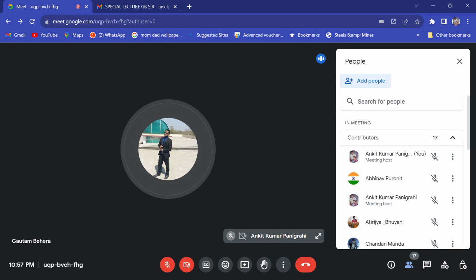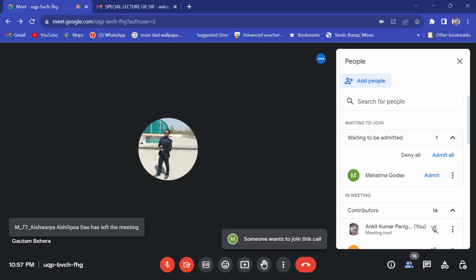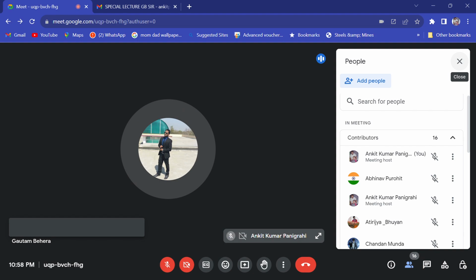Two things can be done, right? Either you purge nitrogen or argon into the steel. What will happen if you purge nitrogen or argon into the steel? It will reduce the partial pressure of dissolved gases. How? Because total pressure will depend upon the pressure of these gases as well as the pressure of argon or nitrogen, right? So obviously that means the dissolved gases are getting diluted by argon or nitrogen. So the pressure will decrease. If the pressure decreases, then it will come out easily.